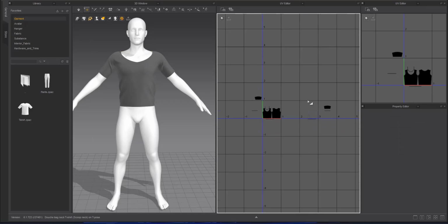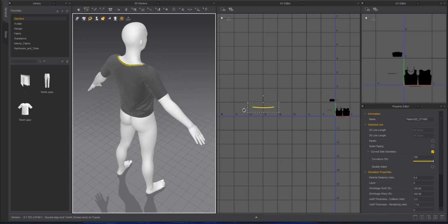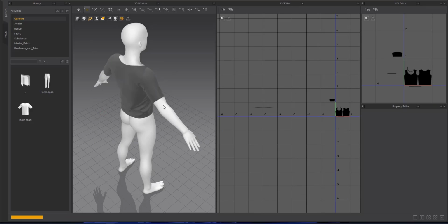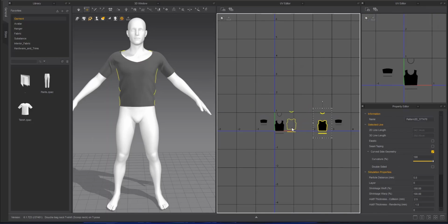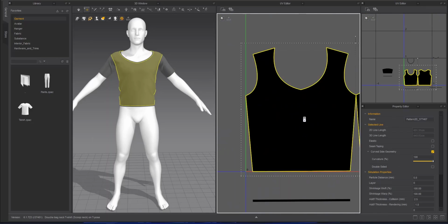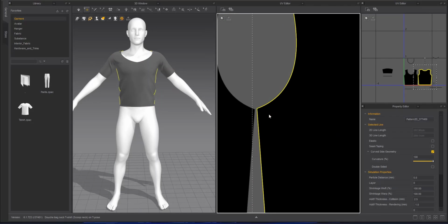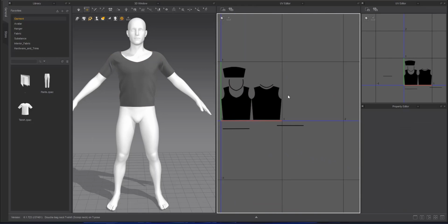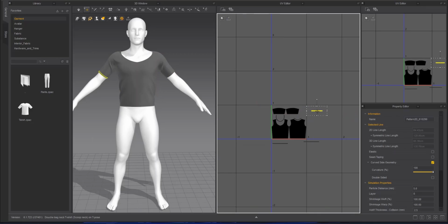To do this, at the top, change the toolbar to UV Editor to enter the Unwrap toolbar. So far, no automatic unwrap tool has been added to this version of Marvelous Designer, so we have to manually place each of the clusters in UV. There are several things to consider. If the symmetrical paste is used when making clothes, it is necessary that when making UV bonded clusters, it should be completely mirrored. Otherwise, when making normal material, the fabric in that series of parts is made in the opposite direction.